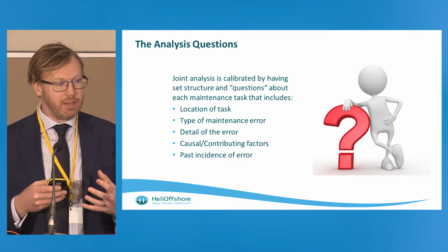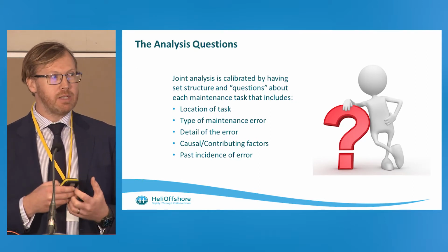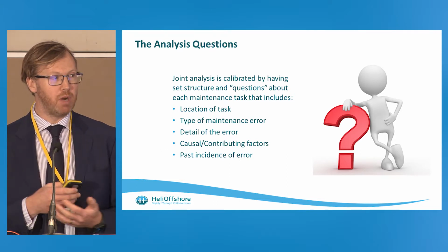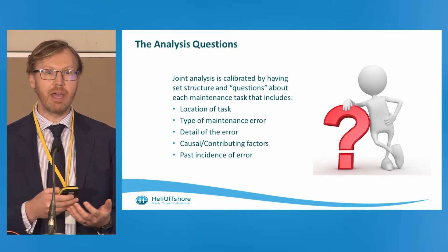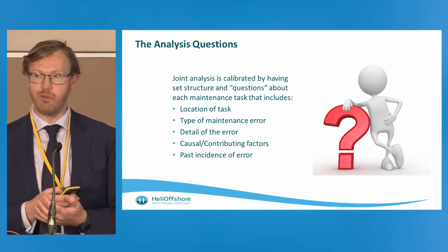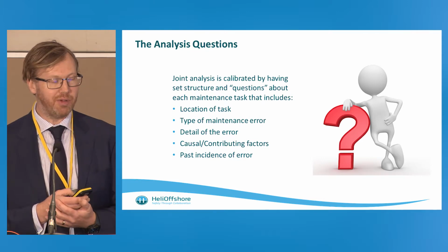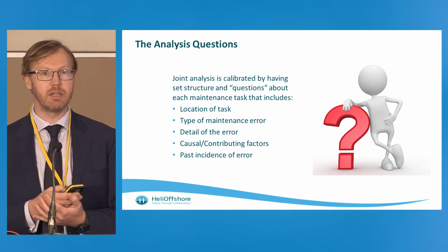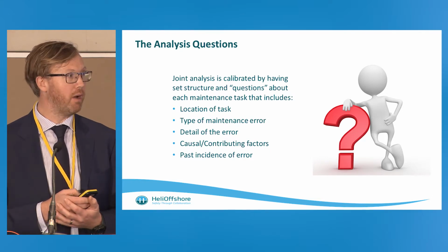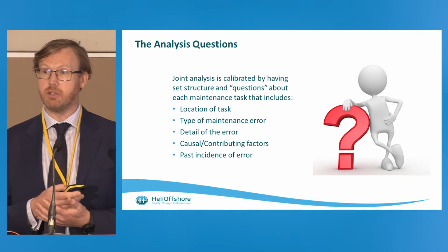So trying to bring that information together, and critically bringing on some work that Airbus Helicopters did related to the contributing factors to error. So they'd done some analysis of errors that they were aware of, and said there were 5 key things that contributed to maintenance error. The first one was accessibility to the component.